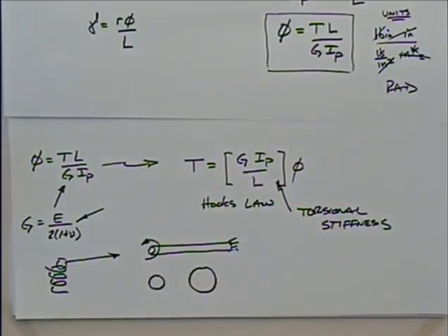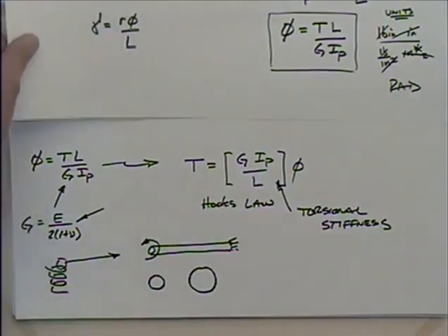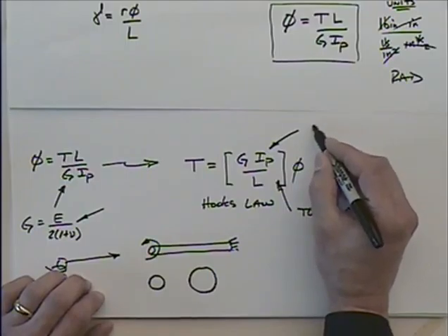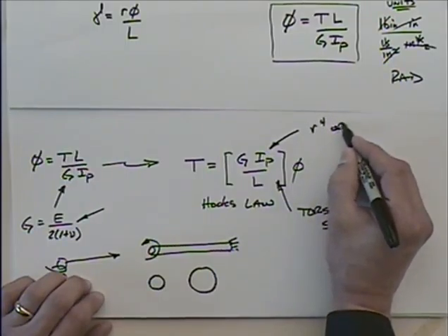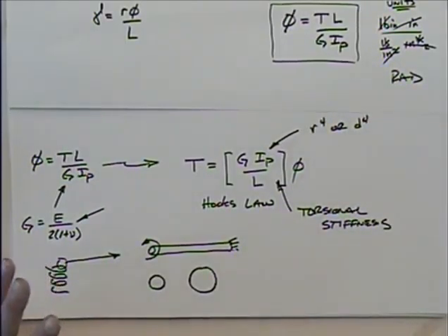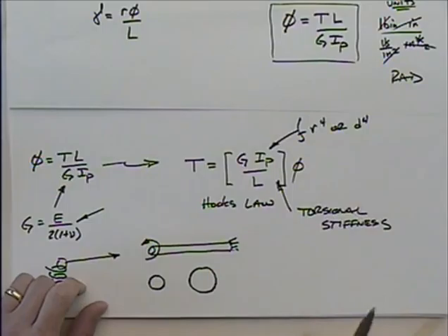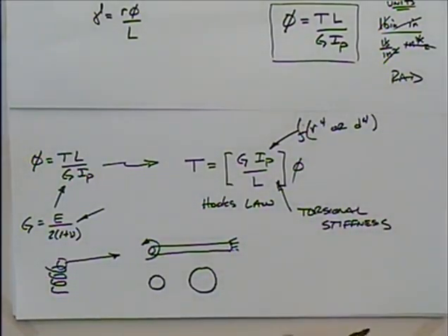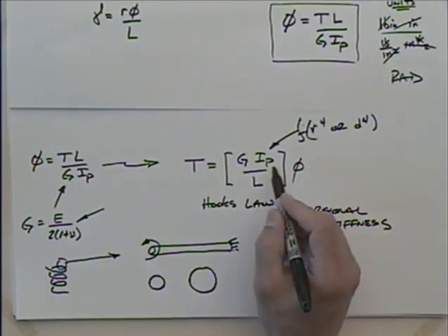A lot of times people will talk about sway bars, and they'll talk about going from a 1-inch diameter sway bar to a 1 1/8, and you might think, well, that doesn't make much difference. But remember, what are we doing for the polar moment calculation? That is r to the 4th or d to the 4th. We handle those a little differently, but we're taking that dimension to the 4th, aren't we? So when you start taking those small distances to the 4th power, that can have tremendous implications.